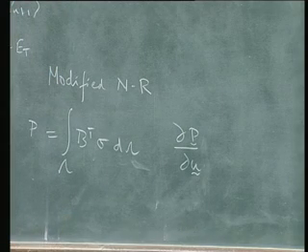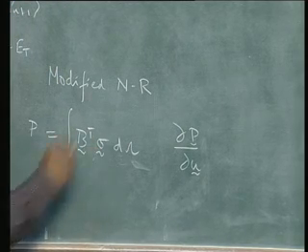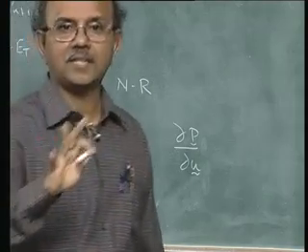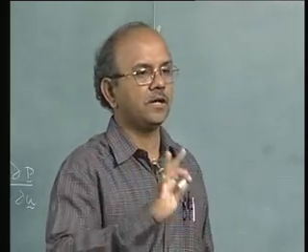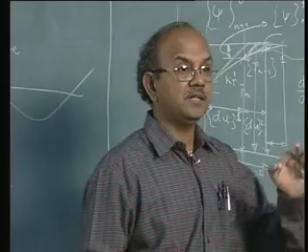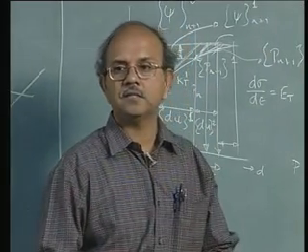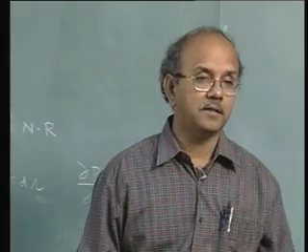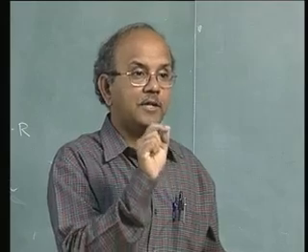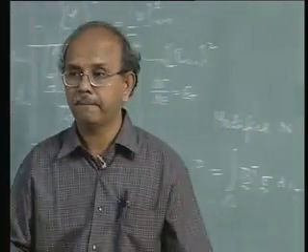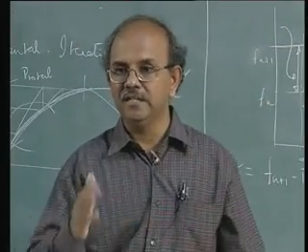Let us see what we have to do. Note that both of them are not scalars, and that right now B matrix is our strain displacement matrix. Let us say it's a constant strain displacement matrix, and we do not have any other things inside it. In other words, we are looking at small deformations where my strain definition, which I had used in my earlier classes, is valid. I am right now putting a rider, understand that rider, that it is not that I can use that B which I had defined in my earlier classes, that strain displacement matrix, all the time. These are linear strain displacement.